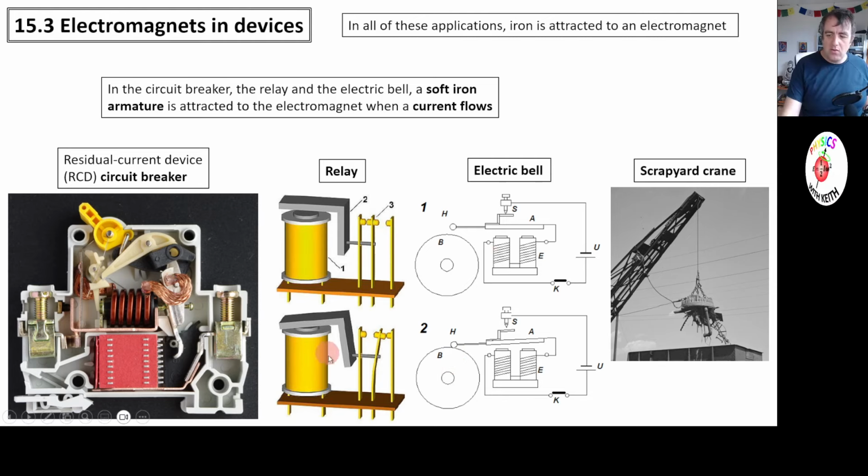A relay. So a relay is a way of controlling a very high power circuit, switching it on and off, using a very low power circuit. It's very commonly found in things like cars, or I worked at McDonald's for many years. The McDonald's grill, the heating element in the McDonald's grill is a very high power heating element. It's going to hold those grill platens at 177 degrees Celsius at the bottom and 218 degrees Celsius at the top. And they're open to the air, so you have to constantly be heating those platens.